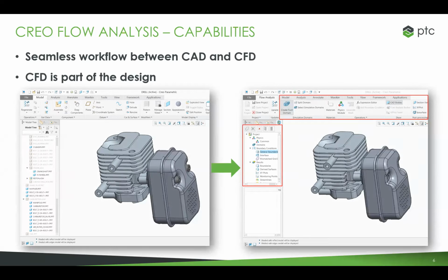And you get the tree down the side, and you're able to run your analysis. But as soon as you click back over into your modeling tab and you make changes, your analysis model that you're running the simulation on is also going to update with those changes, right? Because it's the same CAD model. You're just running an analysis on it in the session.